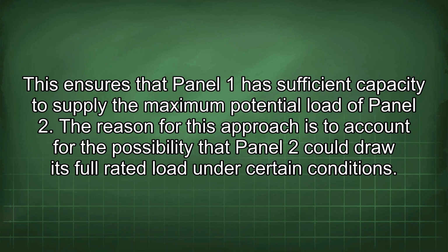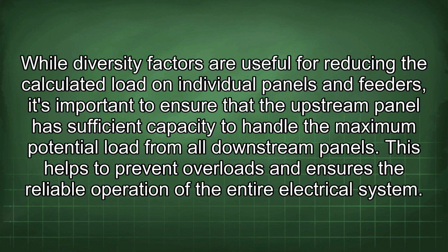While diversity factors are useful for reducing the calculated load on individual panels and feeders, it's important to ensure that the upstream panel has sufficient capacity to handle the maximum potential load from all downstream panels. This helps to prevent overloads and ensures the reliable operation of the entire electrical system.